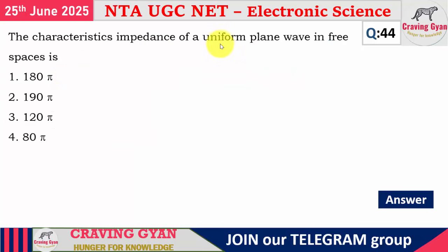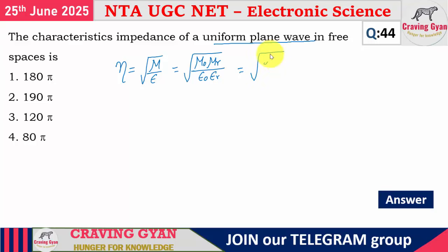The characteristic impedance of a uniform plane wave in free space is given by eta equals root of mu by epsilon. You can write mu as mu naught times mu r, and epsilon as epsilon naught times epsilon r. You can rewrite this as root of mu naught by epsilon naught into root of mu r by epsilon r. Mu naught is 4 pi into 10 power minus 7.